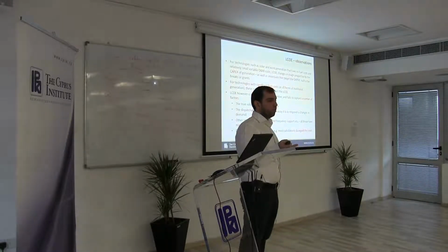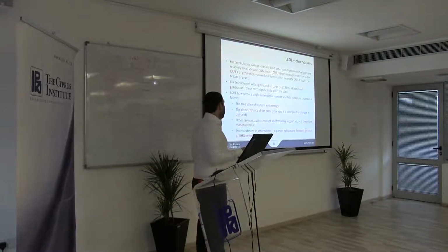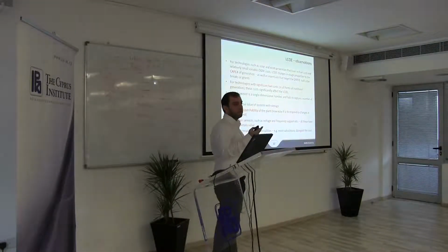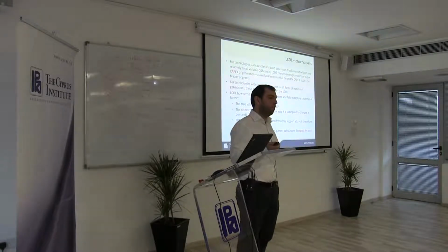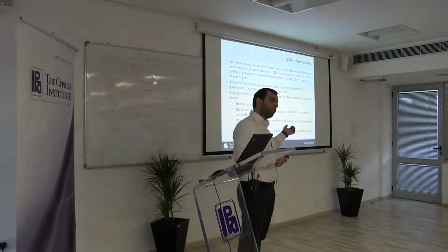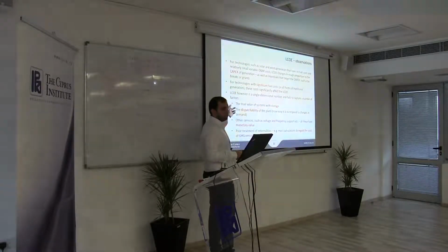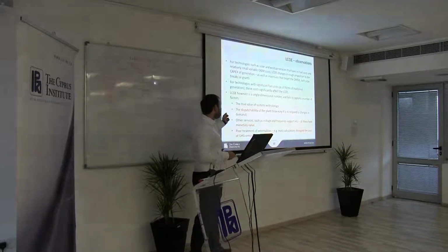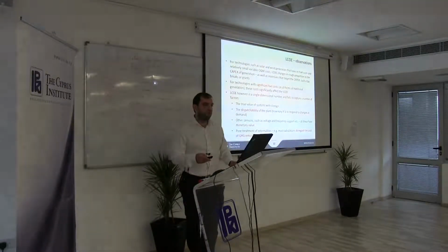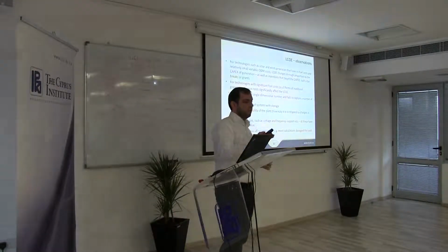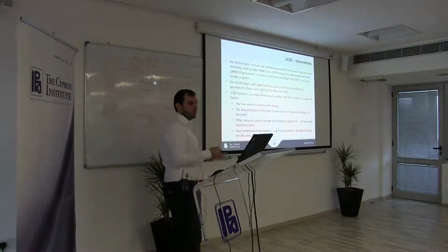But if that technology has no storage, it can only produce basically when there is sun. So even though the LCOE of the technology might be, let's say, 10 cents as compared to 12 cents for a fossil-fired diesel generator, you can't rely on just the technology just because it has a lower LCOE. The time variability and the availability of storage also need to be taken into account. Similar concept, the dispatchability of the plant. So how easy is it to respond to changes in demand? Can we ramp up the generation of a plant or not? This is much trickier in the case of renewable energy technologies in the absence of storage.